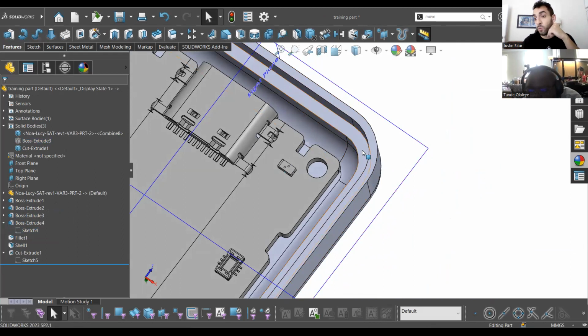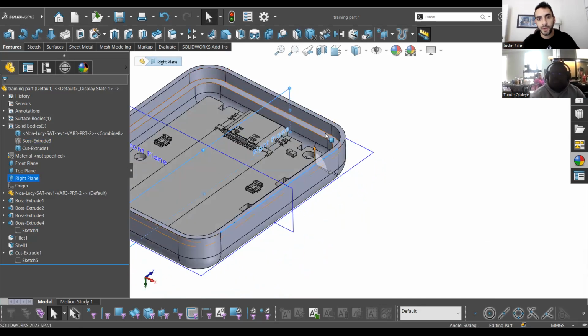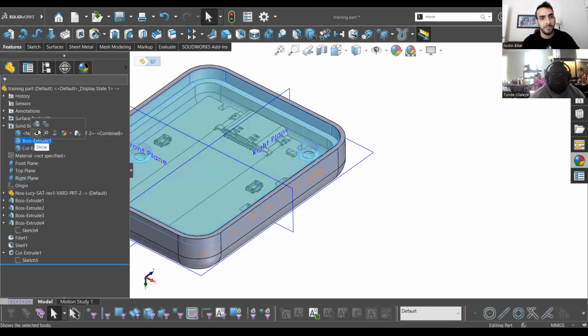See, that's offsetting at 1 millimeter. So this from here to the center line is basically 1 millimeter wider than the base plate is from the center line, right? We're offsetting at 1 millimeter. So we have this 1 millimeter lip all the way around the base plate.